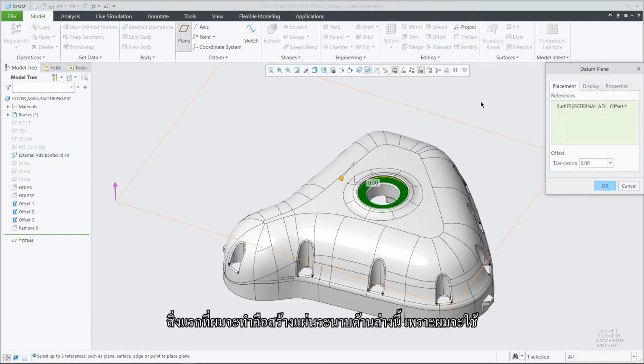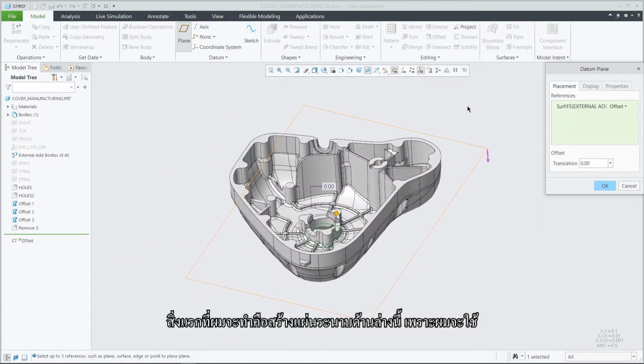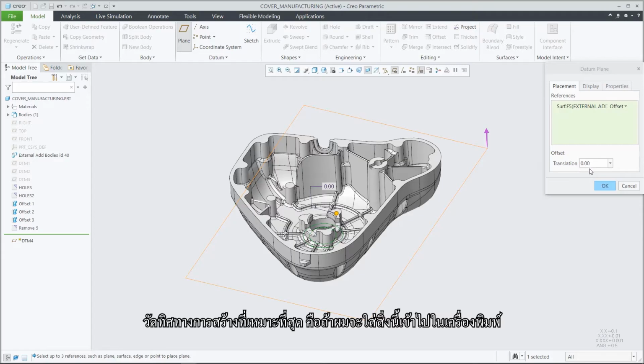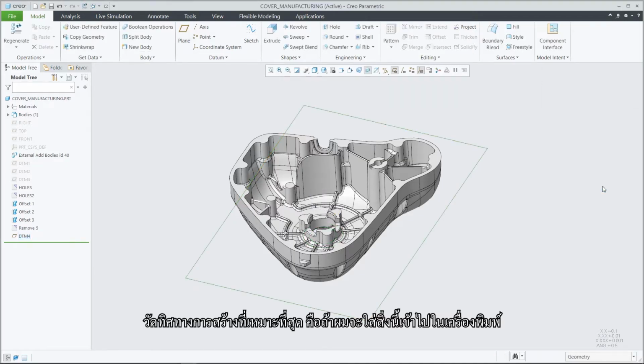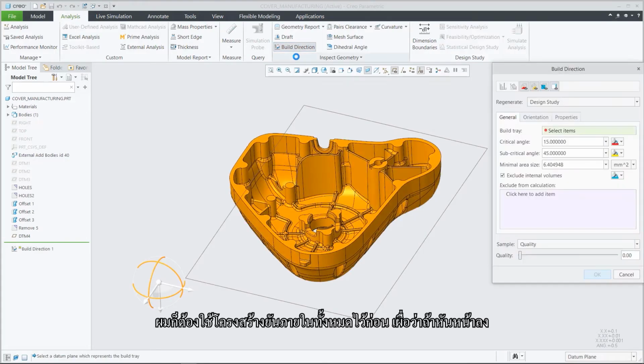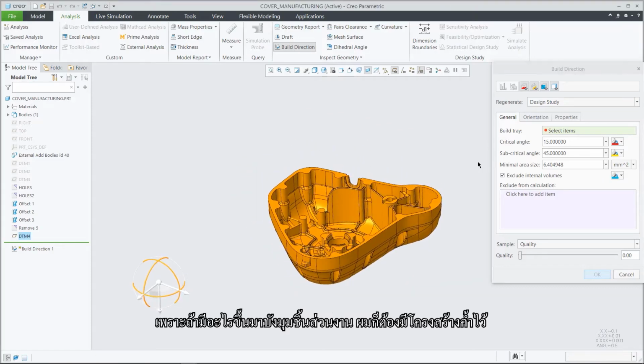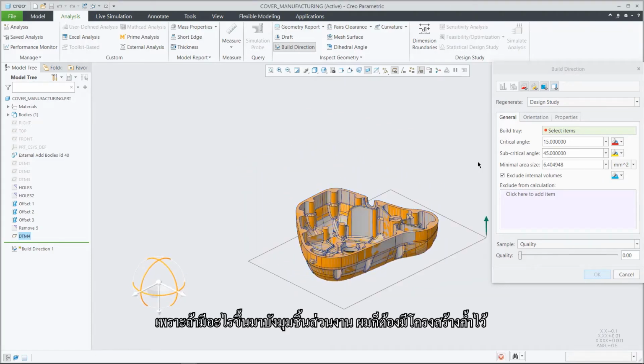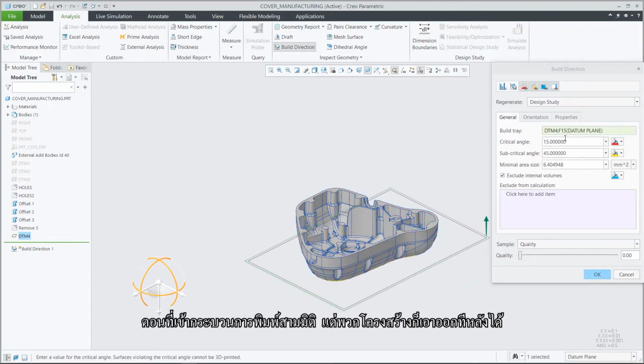So the first thing I'm going to do is build a plane here at the bottom because I'm going to use that to determine the optimal build direction. This is an issue of if I just put that flat into my printer, I'm going to have support structures over almost the whole interior here, assuming it's facing down. Because if it's anything over a certain angle, I have to be able to put support structures inside the 3D printing process, and those have to then be removed later.